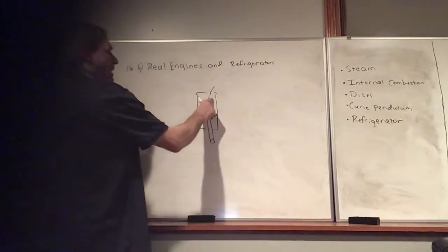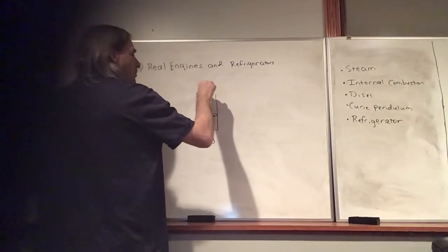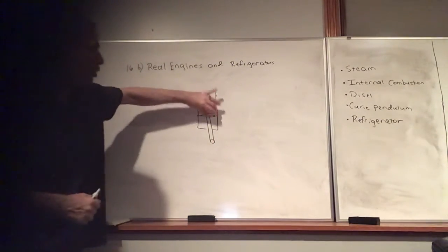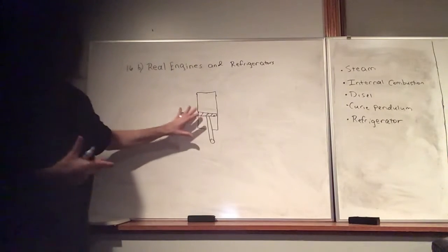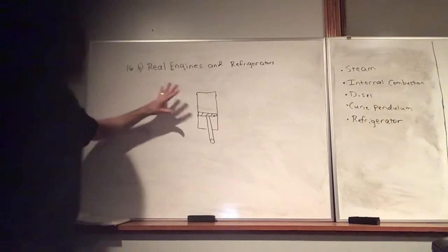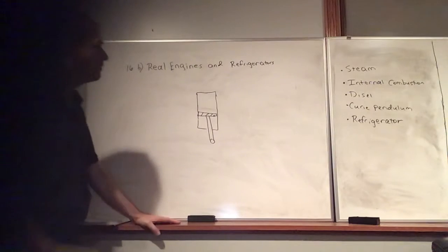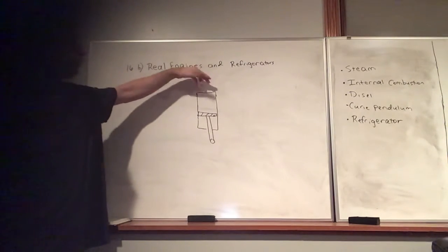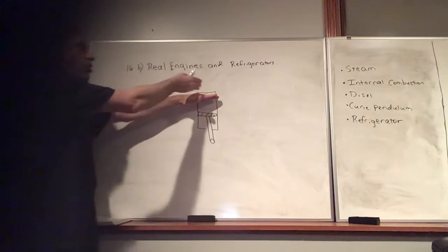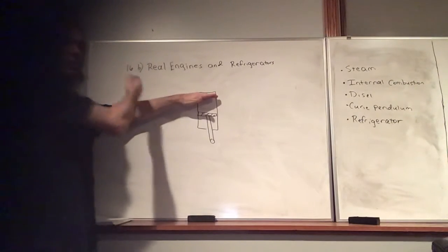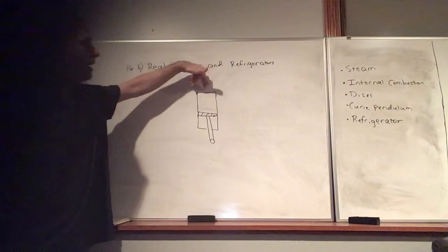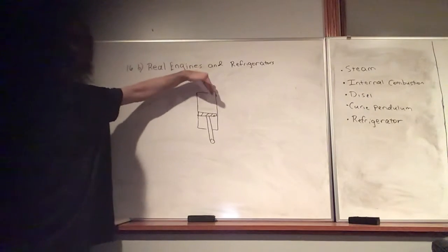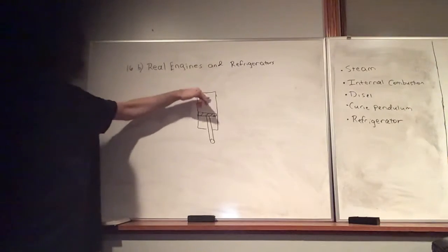and then you open a separate valve. And the piston goes up again and pushes all the gas and what's left of the burning mixture out into your exhaust system, and then that leaves your car. And then you're up at top, you've completed the exhaust cycle, cleared the cylinder, and then you close that valve, open the intake valve, pour more gas and air into it.